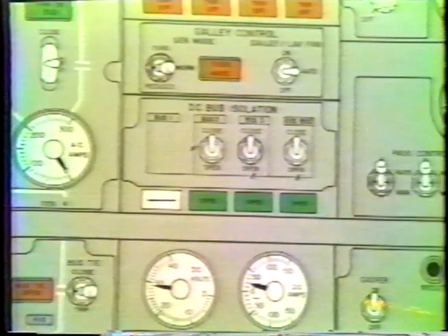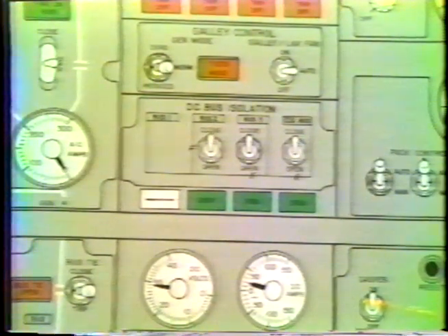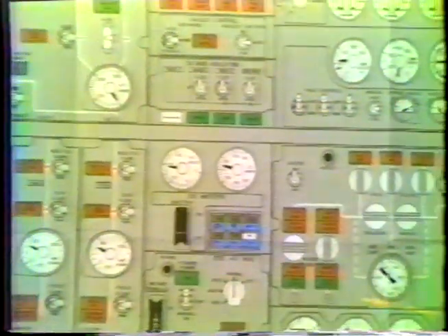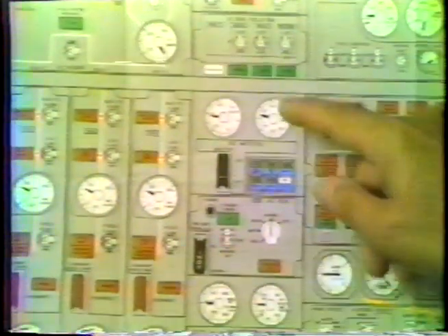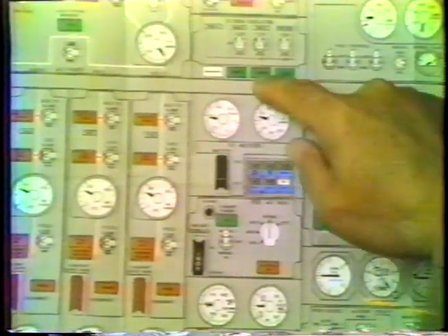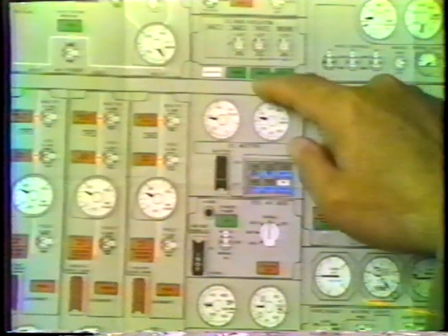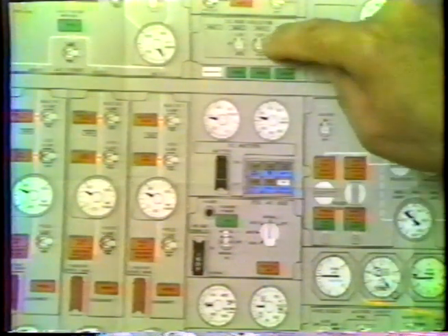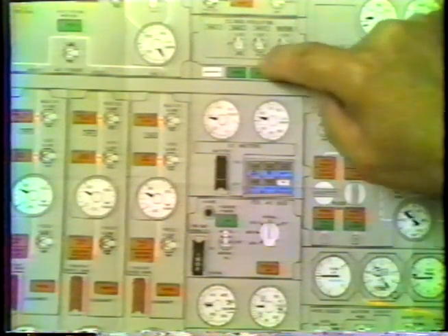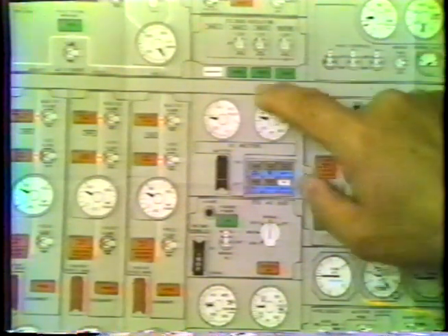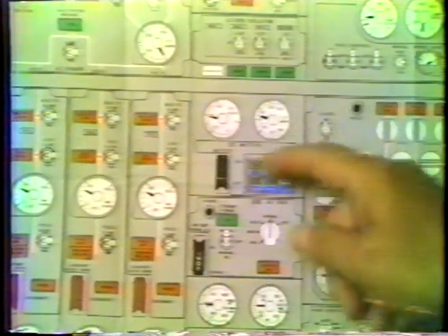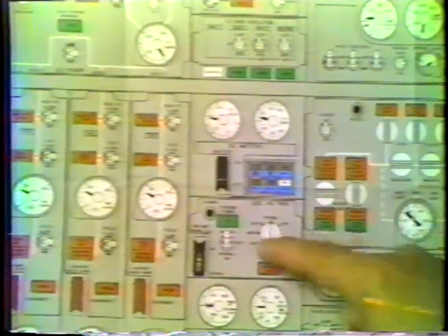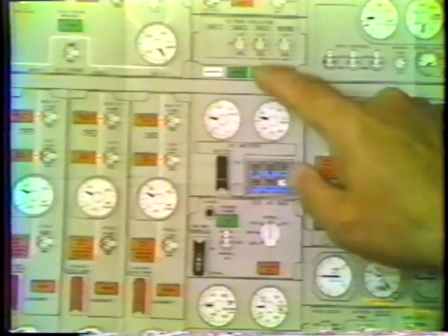And if Essential power is moved out of the normal position to either generators 1, 2, or 3, and that generator is available to feed Essential AC power, the number 3 DC isolation switch will automatically come open and the light will come on. The switch itself will not move, but the light will come on and it will effectively divide the DC bus so that buses 1 and 2 are connected together and buses 3 and Essential are connected together. If Essential power is moved back to the normal position, the bus will automatically close.